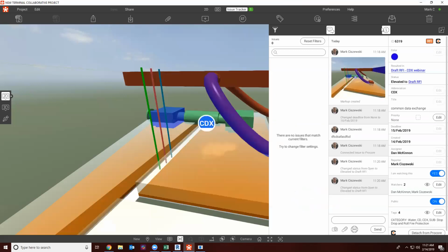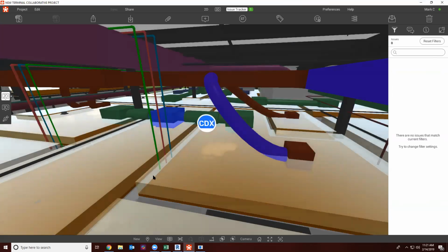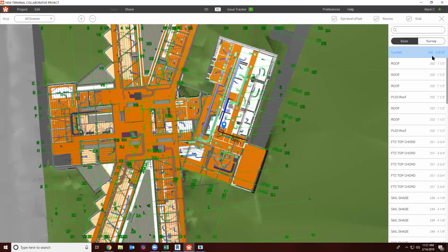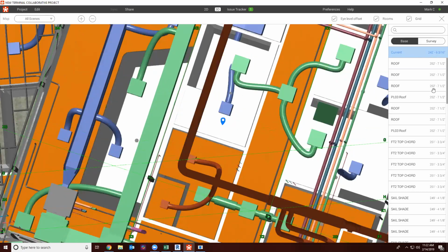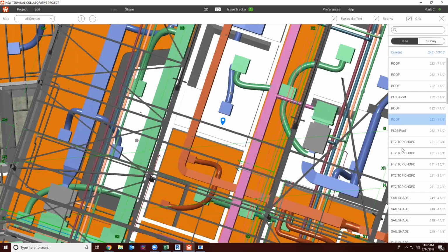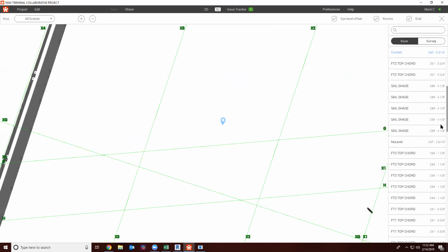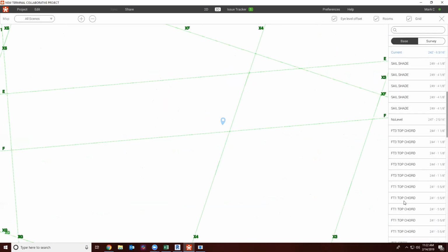And what you'll notice is that if we want to unsection this, we can get an idea of where we're located within the model. If I select 3D, we can see those pipes that we highlighted. If I press M on my keyboard, it's going to show me my specific elevation. I can scroll in here. It can even tell me exactly what direction I'm looking. We can go to different floor plans to see where that's going to fall within a different level or what room it's maybe above. So I'll jump into, let's find a level 2-1.